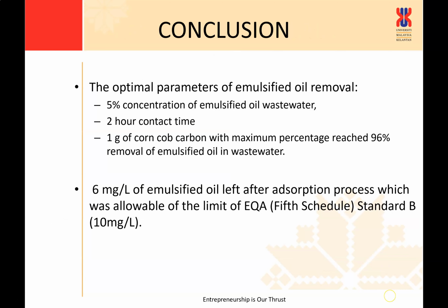For the conclusion, the optimal parameters of emulsified oil removal were obtained, which are 5% concentration of emulsified oil wastewater, 2 hours contact time, and the use of 1 gram of corn cob carbon, and the maximum percentage of oil removal reached 96%. It can also be concluded that 6 mg per liter of emulsified oil was left after the absorption process, which was within the allowable limit of EQA.